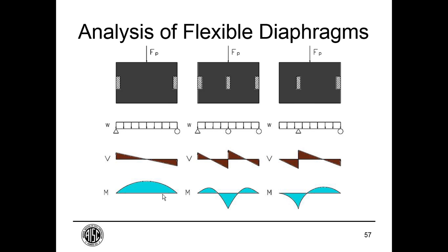I strongly recommend that no designer ever assume that you know exactly where it's going to go to zero, or put in anything that has zero axial force capacity on those chord lines. Instead, you can draw envelopes around these.